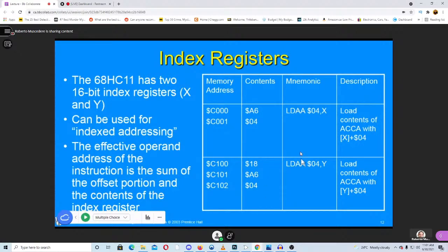So the obvious benefit is I have an extra index register. The problem is it takes an extra byte of code every time I use a Y register, and it takes an extra cycle to run this piece of code because I have to fetch the pre-byte, right? That's the compromise. That's the way it is. Now, you may think this is unusual, but it's actually quite normal. So if you bear with me just for a second here, I will show you a great example of this, if I can find it. There it is.